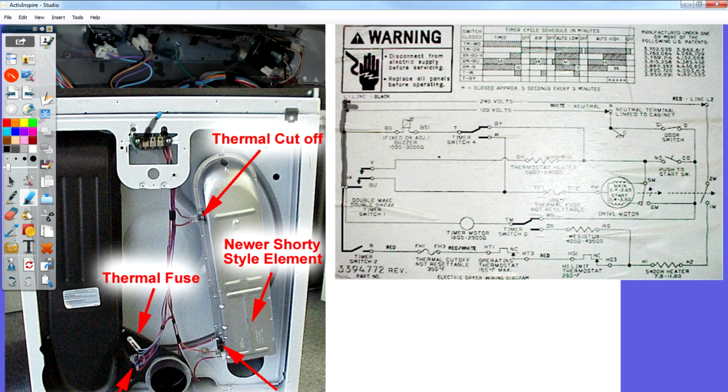So that black wire is running up through this harness here, and it's connecting to the timer right here. I don't know if you can see that too well. Let me just go over it with a yellow, just so it appears a little better. I tried to follow the color code, but that's not going to happen. So that's this line right here. Now we go through the timer. We come out of the timer with a red wire. Where does it go to?